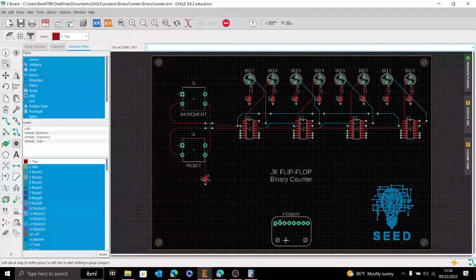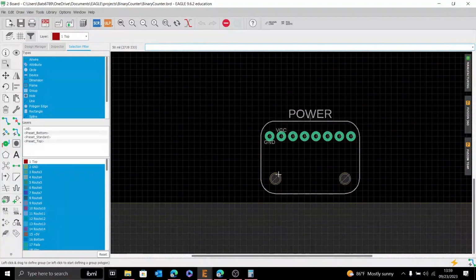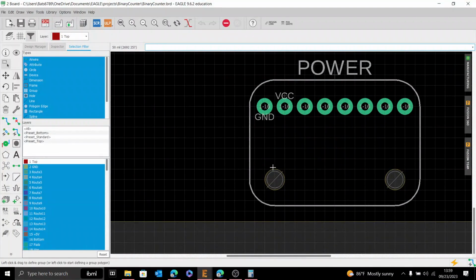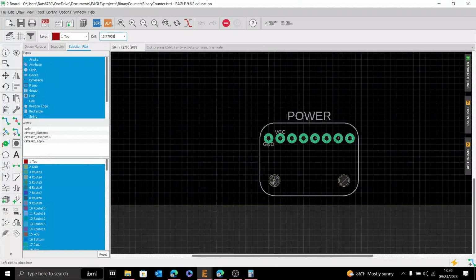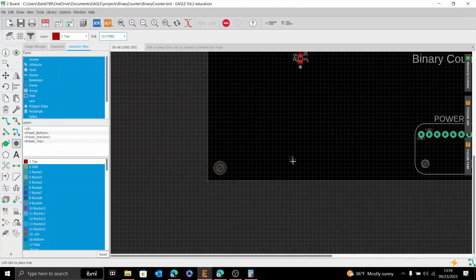But there's my nicely laid out board, and let's take a minute to explain this because I forgot about this. So you see the difference between this hole and this hole. This is a via, meaning there's exposed metal for solder to connect to and make connections between layers. This is a hole. That's the difference. It's just a hole, so no copper connections, no need to worry about stuff like that. And so if you want to add a hole, you click on the hole button. Spoiler alert, the hole button adds a hole of whatever size you specified. These, I think we saw, were 100 mils or something like that. I don't remember now. But I know these are M4.